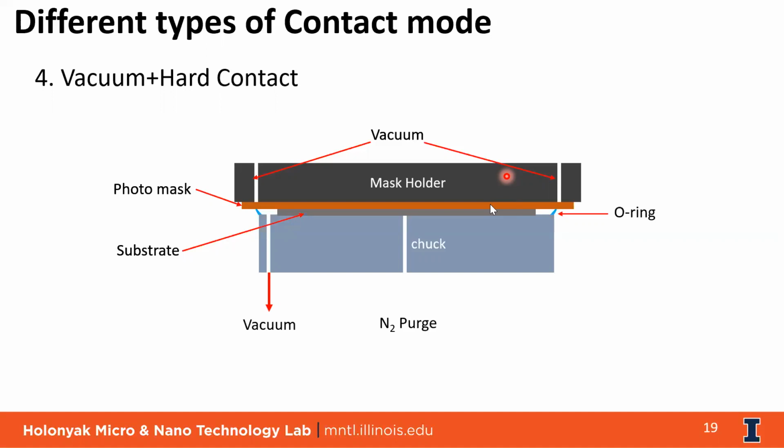Yeah, sure. But what I mentioned, either solvent or soap water or piranha cleaning, are the mostly used ones. But RCA1 nobody prefers because with RCA1 you'll be using very strong chemicals, which can have some effect on the glass as well as the chrome. So I wouldn't recommend using RCA1. The best option is either soap water clean or a solvent. If that doesn't work, then you can go for a very diluted and quick piranha clean rather than using RCA1.